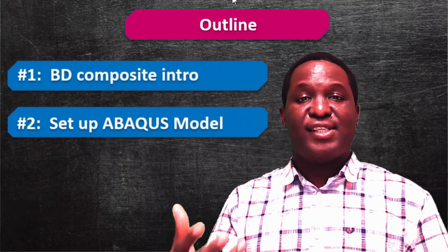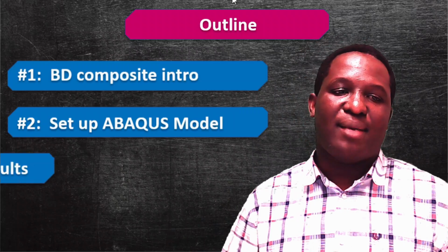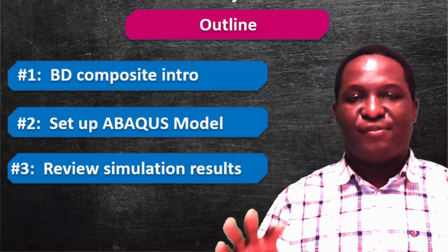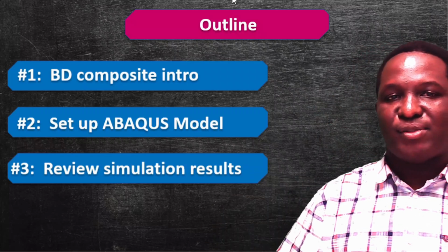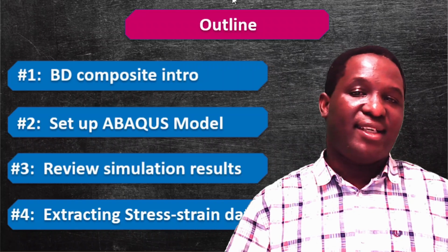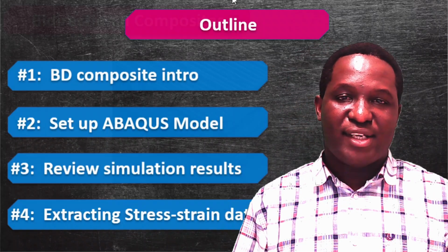And then we look at setting up the model in ABAQUS. How do you actually set up this RVE simulation within ABAQUS? And then we go on to review the simulation result. This review will be based in terms of the contour plots, what is unique about the deformations that we're seeing, and then finally I'll show you how to extract stress strain data from these different simulations.